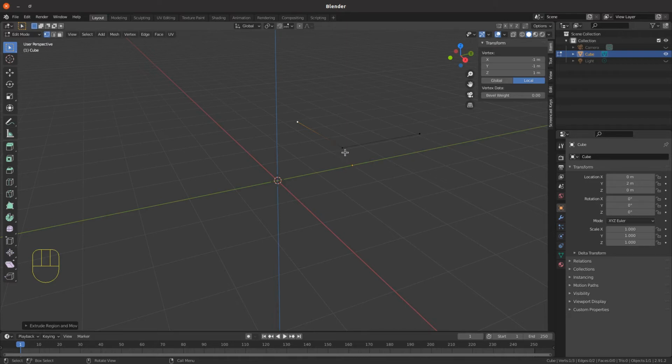And now if we select all of those, another thing to note while you're selecting, the last vertex selected is highlighted white where the others are highlighted orange. That's because the last vertex selected is always the active vertex, and it can have effects on when you're snapping objects together, which we'll go through in future tutorials as we're building models.